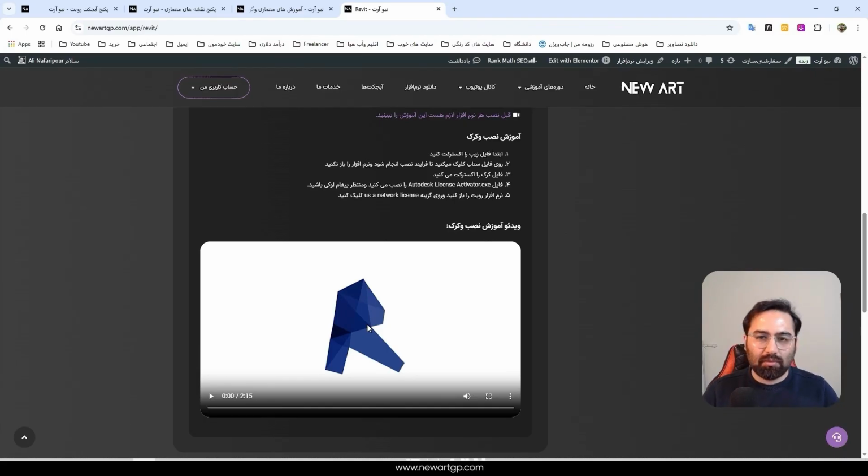That means you might see a formula added in a new version that didn't exist in the previous version. So if Revit tries to open a higher version file in a lower version, it will run into problems. So I decided to make it so that lower versions can't save or open higher version files. So the user won't be able to do it anymore. They have to open it with the same version so they can use those formulas and parameters. To explain a bit more, it's like you have a wall with a set of settings.